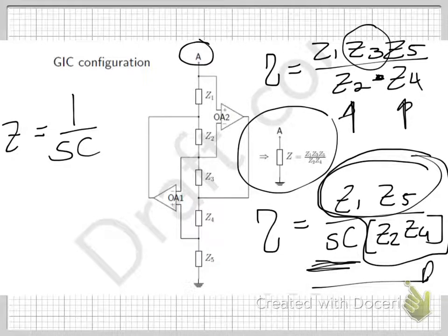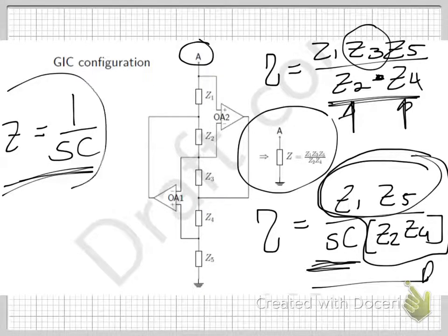You can also simulate an inductor by replacing either Z2 or Z4 with a capacitor, and then that's how you will simulate your inductor.